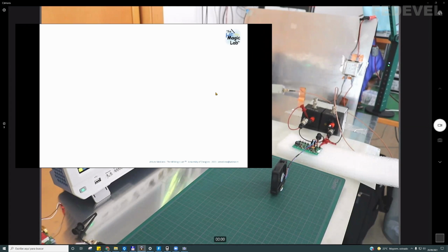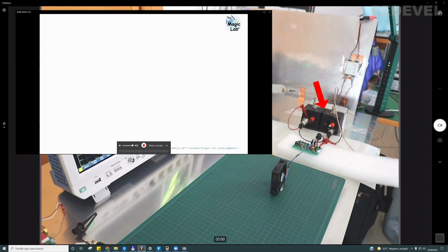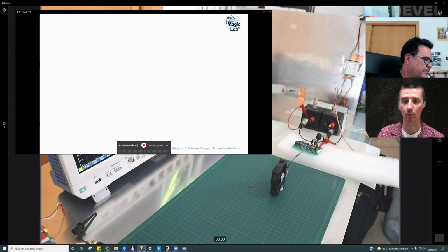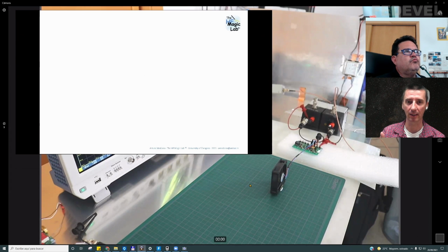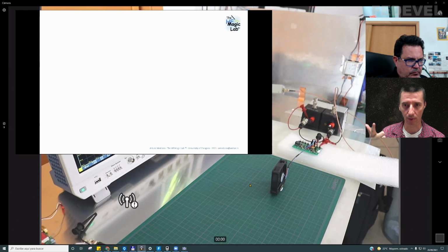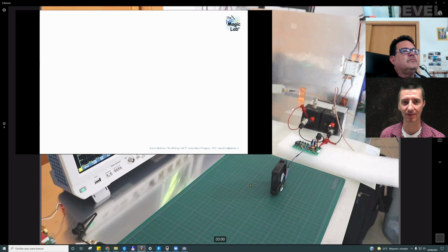So now the question is basically what is inside of these black boxes? We mentioned we need it for three things. We need it for the impedance. We need to have it there to connect our spectrum analyzer, and it's also doing some kind of filtering. But we would like to know what exactly is inside of these black boxes. Okay, so in general, what you can find here is a way to control the impedance you see in your setup system. So you need to offer some known impedance for your system in common mode and in differential mode noises.